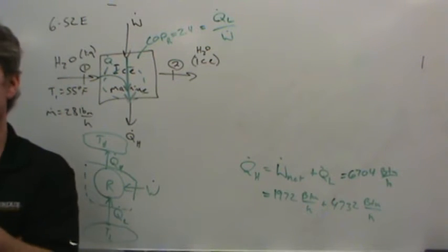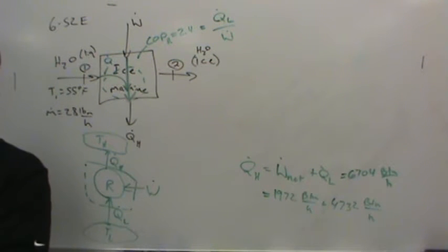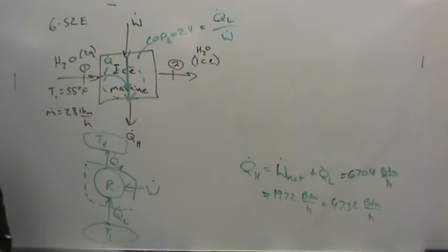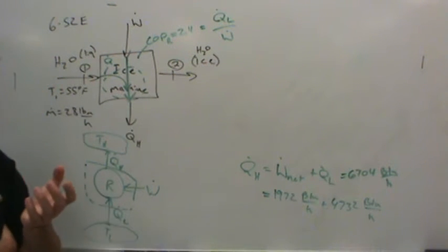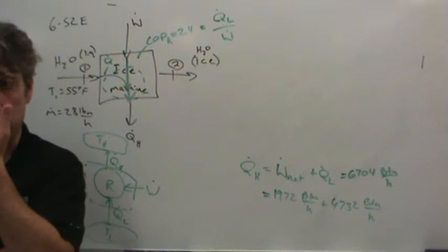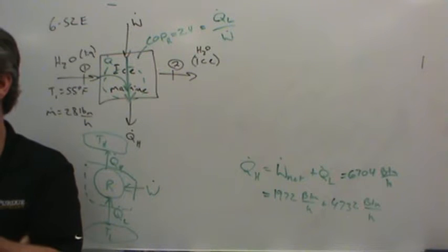a heat pump is also specified based on its ton capacity. It's this idea, right? So its ability to heat a space is based on how many BTUs per hour it can move. And if it can move 12,000 BTUs per hour, it's a 1-ton heat pump, okay?